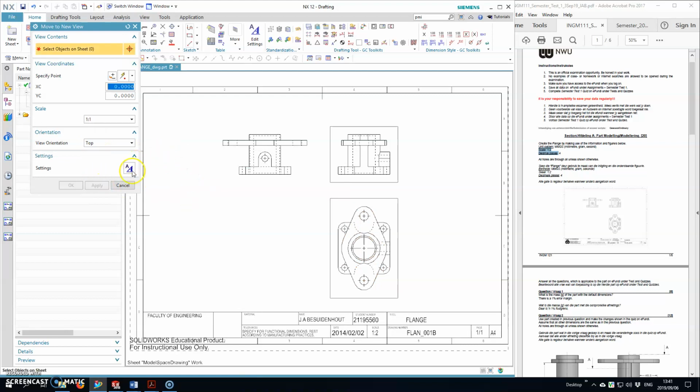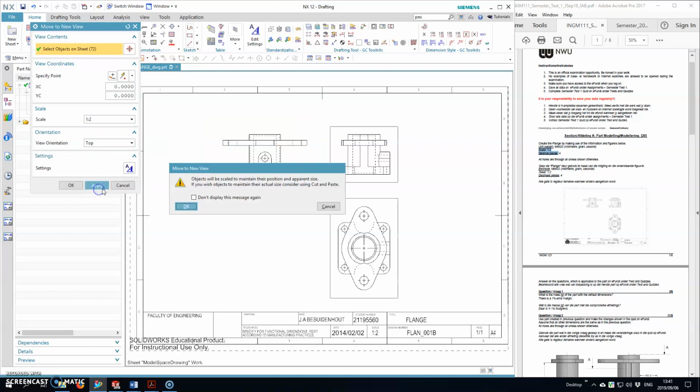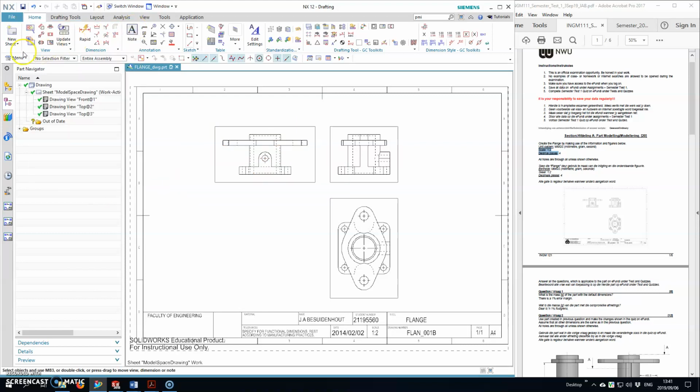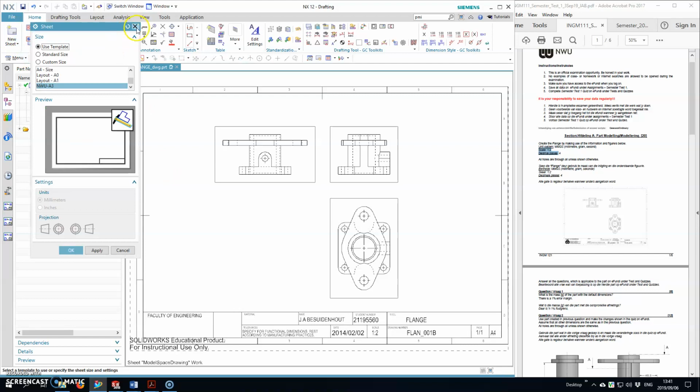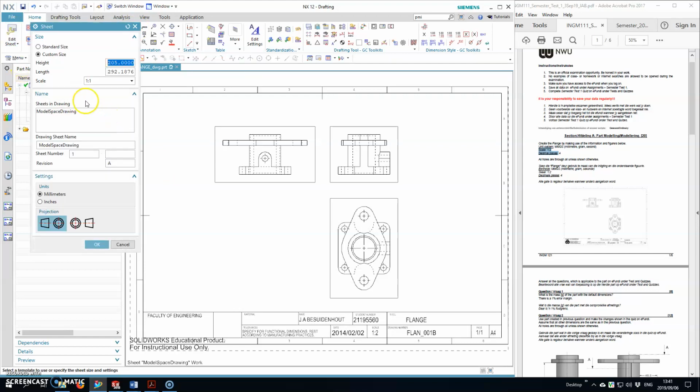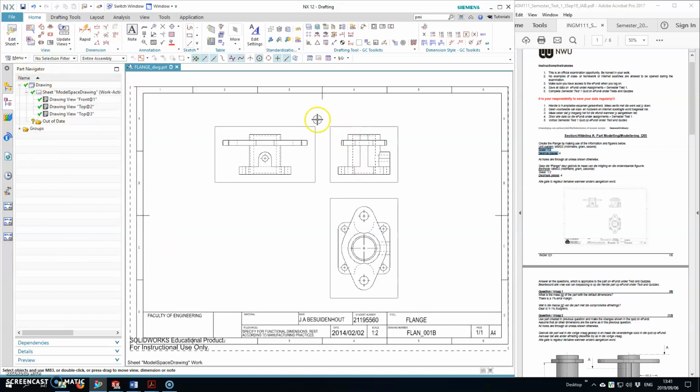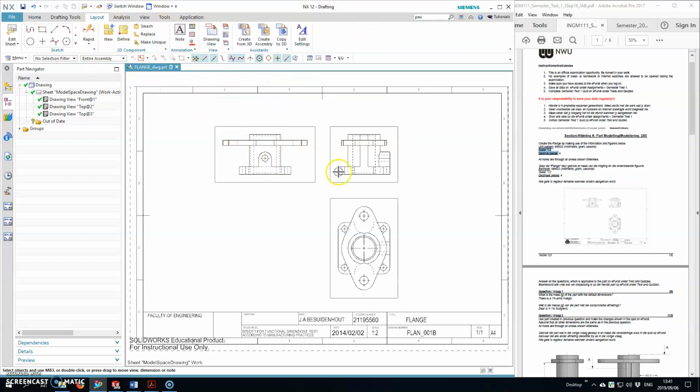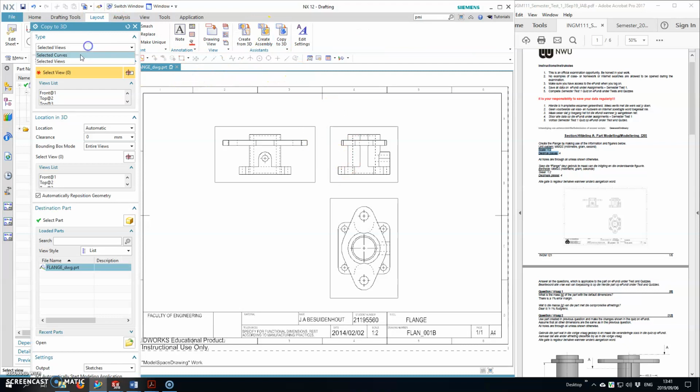It's important that you make sure that you assign the right scale to all of them, right? So you don't change the sheet format here, you leave it as 1:1. Yeah, so you rather just change it here, then you will get the original dimension. So if you ever measure these things, it would be half scale. Okay, so next thing will be to copy our views to the 3D environment.